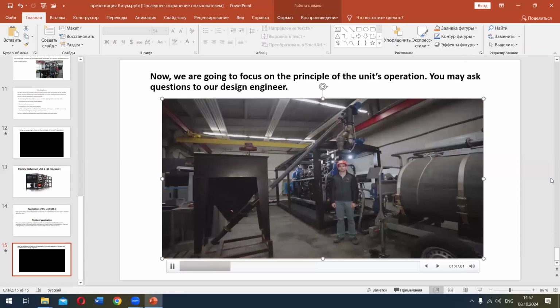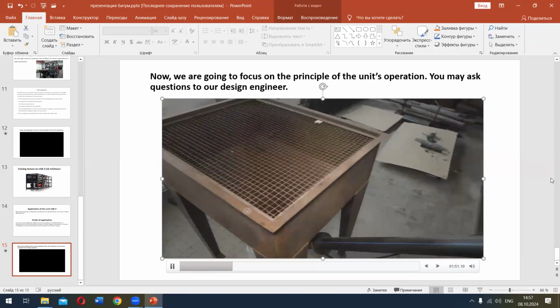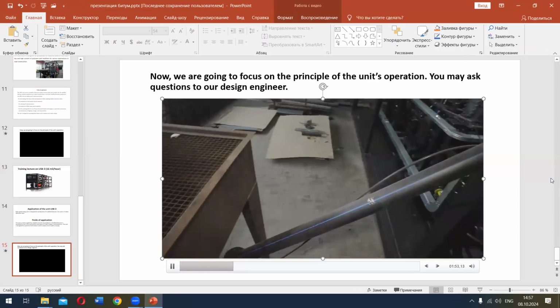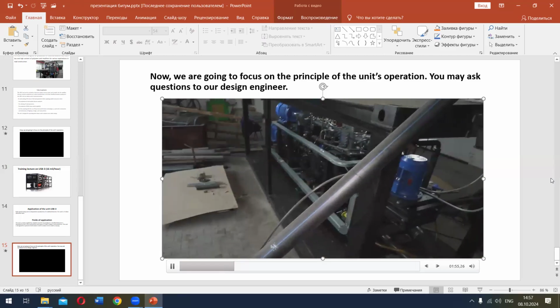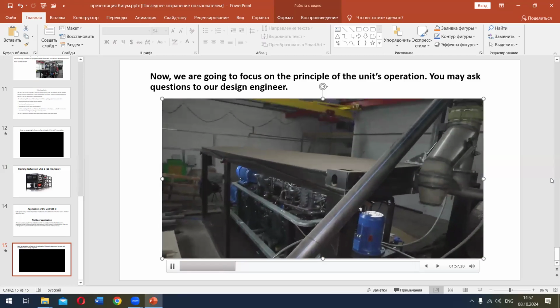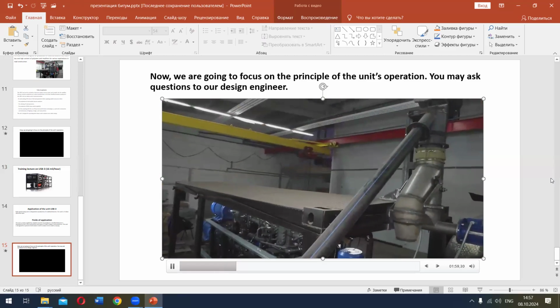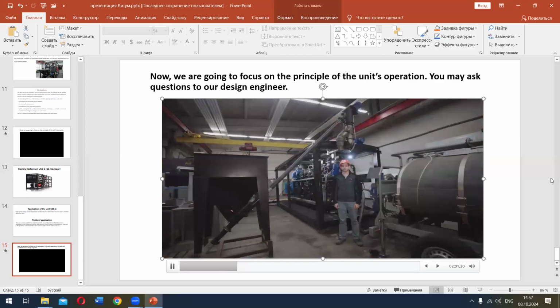The process of preparing the unit for operation includes calibration. In order to calibrate the spiral conveyor, it is necessary to fill the polymer hopper with polymer and, having switched the splitter gate valve to the idle hose, consume the polymer by stopwatch timing. In order to calibrate the adhesion additive pump group, we should connect the pump group to the additive containing tank and then do the priming.